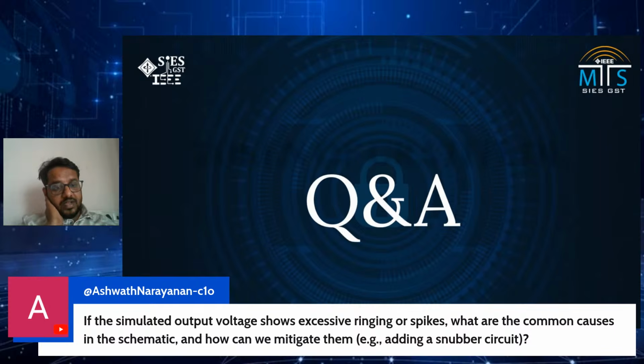So excessive ringing happens if you have, like I said, a bigger parasitic inductor which stores the energy, and it forms a resonating circuit with the parasitic capacitor of the MOSFET. So it causes ringing. What we generally do, like you are saying, is add a snubber circuit to damp out the ringing. Otherwise, we also tune the gate resistor. If you increase the gate resistance, then it will reduce the ringing, but there is a trade-off that it will increase the switching loss also. So there are multiple methods for removing the ringing.